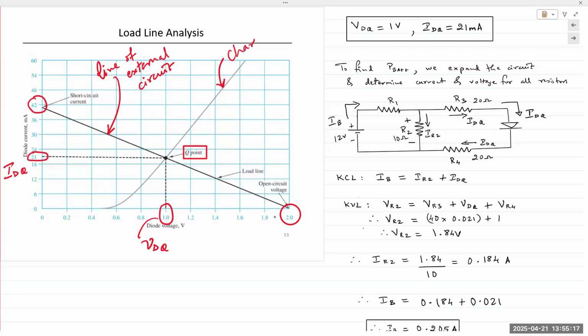Okay. So the external circuit, whether it's a diode or any kind of device. If you perform the lab today, we work with BJTs. We apply DC voltages. When you apply DC voltages, we are forcing that BJT to operate within the parameters of that circuit. So the same thing happens here. We have an external circuit, you have an external power supply. We are forcing the diode to operate within a certain portion of its range. Okay. So in this load line analysis, the operating point is the constraint placed on the diode by the external circuit.